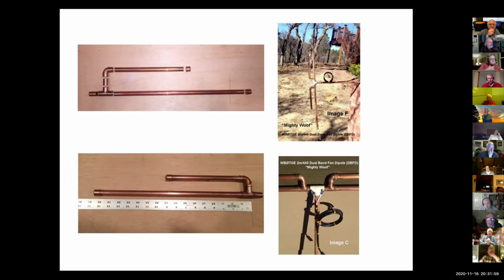Soldering is an easy thing to do. Once you clean the parts and fit them together with flux on them, you want to get a propane torch and start heating the copper pipe. While you're heating it, you take your solder and start touching it to the copper.